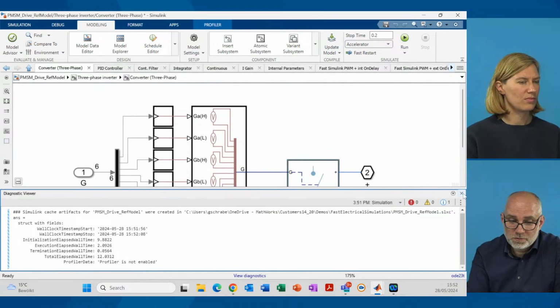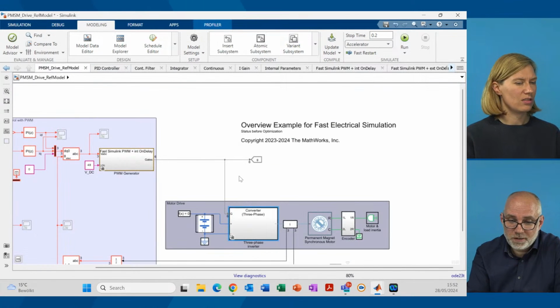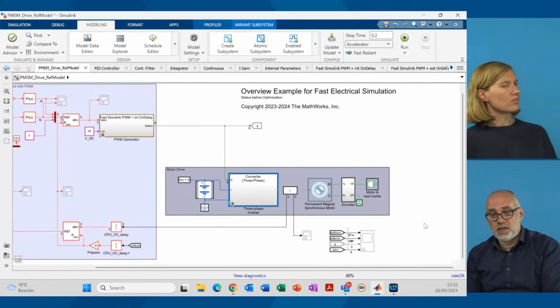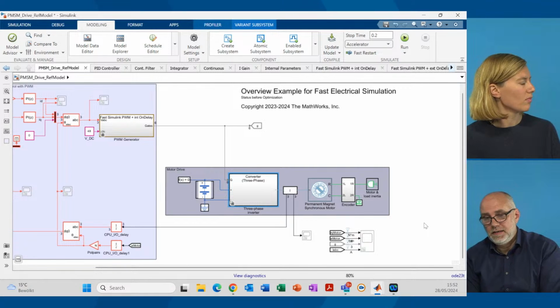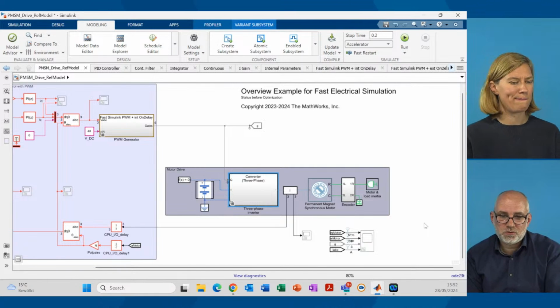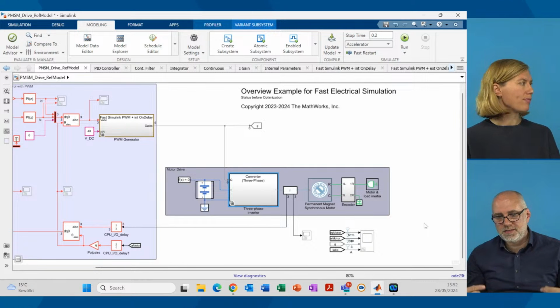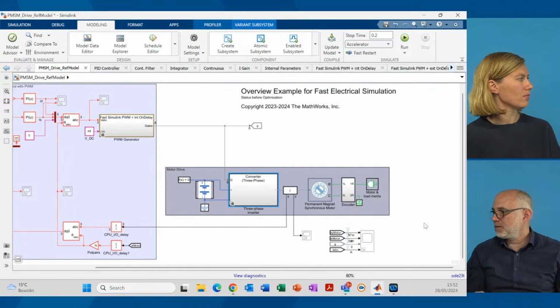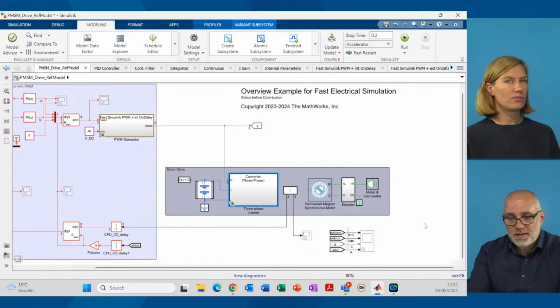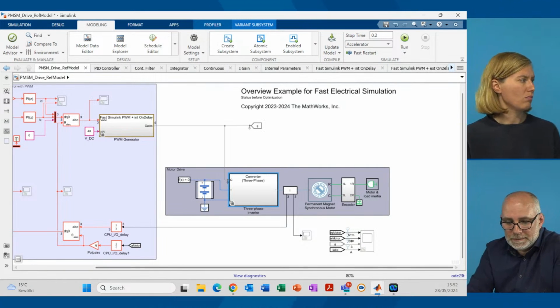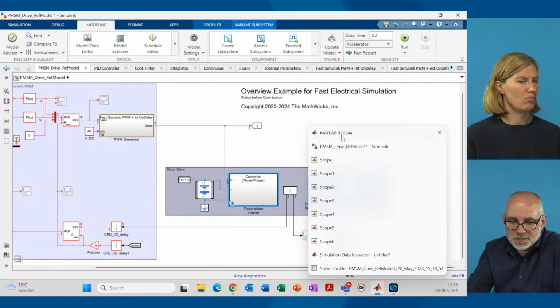For the main things we have shown now, there's only one different thing I want to mention, which you can also find in the video series. If you want to run intensive parameter sweeps with a lot of combinations or test cases, or optimizations, where you have to run a single model again and again with different parameterization, there is another option called parallel computing. It's an option where you can use a script to set up the problem, and I can just give you a short insight.